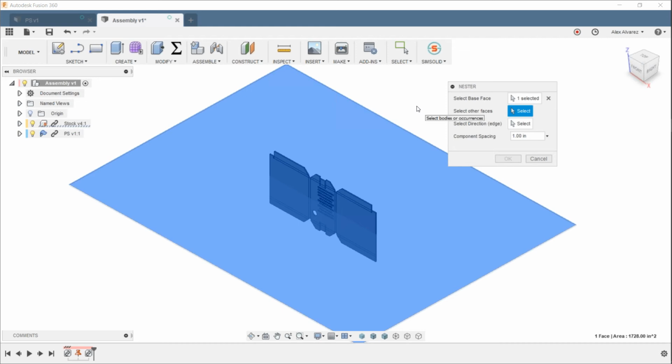I remember doing a sheet metal webinar where I was using a flat pattern, and then I activated the flat pattern, and then I created some sort of CAM toolpath based off of that. With that, if you want to go the route of a flat pattern, you can only have one active flat pattern at a time. But if you decide to go this route, you can unfold multiple components and then bring them all into the sheet size, or into the specific sheet. I just have this single one, but it's going to apply the same way as it would if you had multiple components in here.